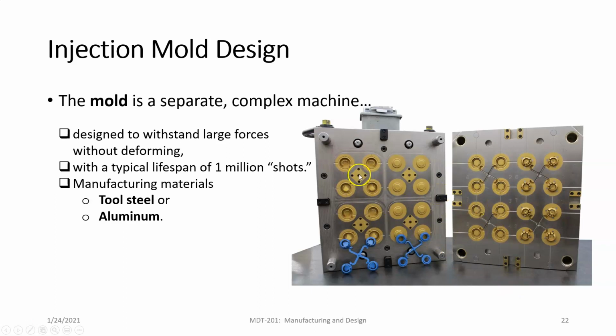It's going to be injected right there, okay? So these 5 holes here and here, this is where the plastic is going to be injected, and then it's going to go through these runners, this kind of X-shaped runner for each one of these, and then through the gate into the part.